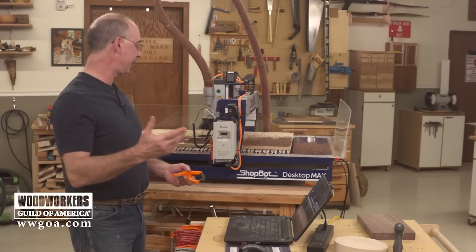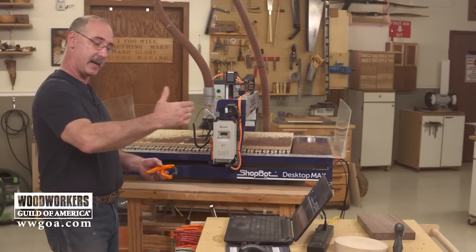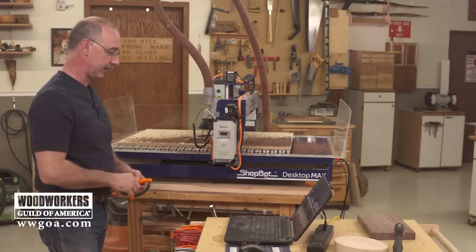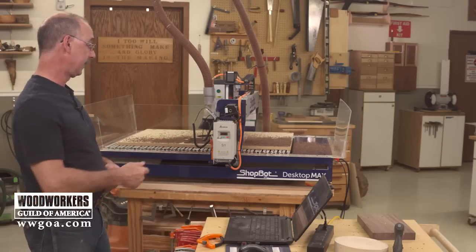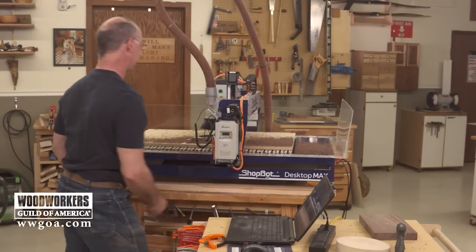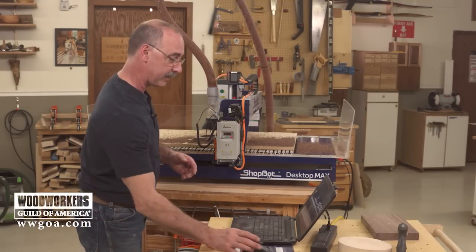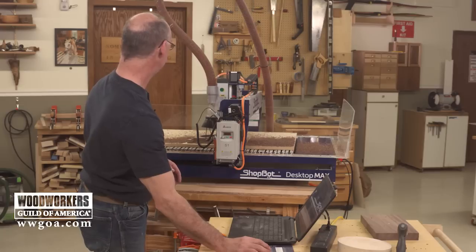So what we were seeing right at the end there, when the spindle was moving up and down, it was leaving the tabs behind. It was cutting the perimeter, lifting, leaving the tab, cutting the perimeter. Next thing we need to do is change cutters. I told you we were going to get to see some of that. I'm going to turn the spindle itself off. It is a router, so we want to make sure that there's no chance of power going to it. I'm going to increase my Z just a little bit so it's easier to get to.